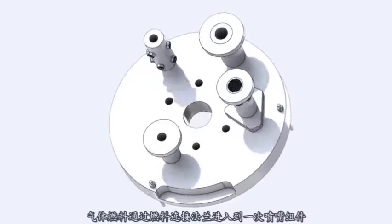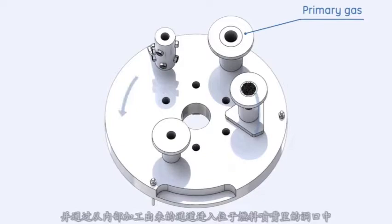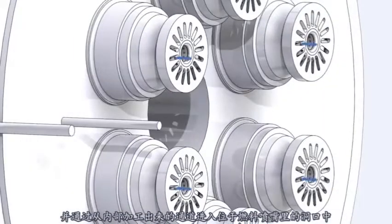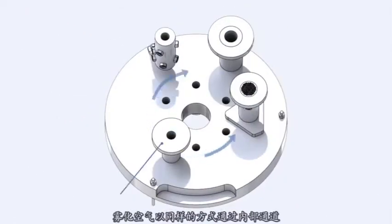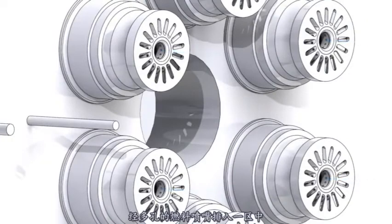Gas fuel enters the primary nozzle's assembly through the fuel-gas connection flange and is routed through internal machined passages to the orifices located in the gas tips. Atomizing air is introduced in the same manner through internal passages and exits to the primary zone through multiple holes on each of the gas tips.